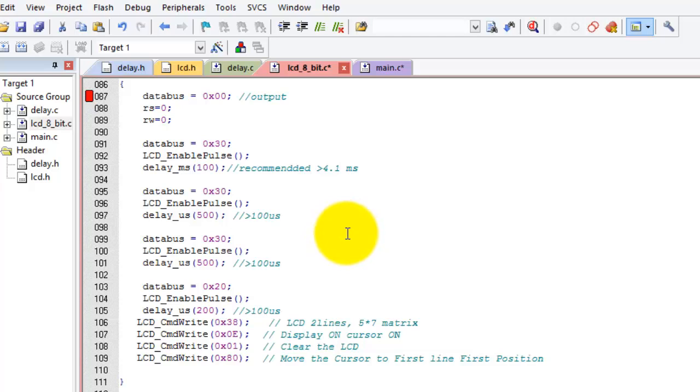What happens is, if you write the code and initialize the LCD in the first part, the controller would boot up and would have already executed this code before the LCD boots up. So the LCD misses all these commands, and hence it is recommended to follow the reset procedure, wherein you reset the LCD with this sequence. You send 303030 along with the enable pulse, and you wait for the specified time. This resets the LCD, and after it resets, you set the LCD mode.